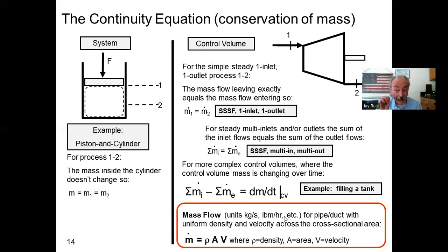One thing that is high probability is calculating the mass flow rate when you're given the volumetric flow rate. So this one is critical for you to remember. M dot, the mass flow rate, equals rho A V, at the inlet or at the outlet, depending on what's given. And remember your textbook might not say M dot equals rho AV. The textbook might say M dot equals AV divided by little v. That's identical to what we're saying here. Remember, little v is the reciprocal of density. M dot equals rho AV. That's an important thing to get in your mind.